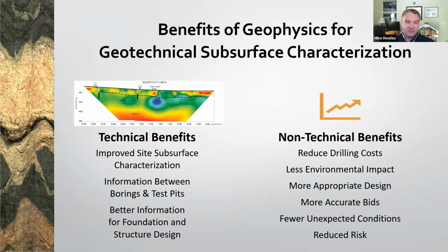Before I get into the electrical methods, here's a quick plug for the benefits of using geophysics in exploration. Non and minimally invasive with less environmental impact, especially compared to drilling. Can reduce drilling costs by interpolating between boreholes based on data, not just blind interpolation. Improve confidence in the geotechnical characterization and establishes a more reliable basis for design and construction, and accelerated project delivery. Many construction delays are attributed to inadequate knowledge of subsurface conditions. A well-scoped investigation program improves decision-making, constructability, and provides time and cost savings.